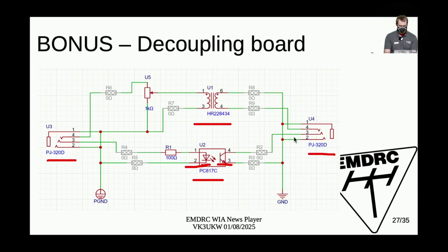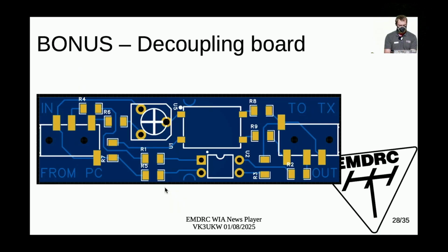You've got a whole bunch of 0 ohm resistors here that I put in, so that if I accidentally flip one of the electrical connections around, I can botch it to make it go in the right direction if I need to cross it over. It also let me do the whole board as a single-sided board by routing traces under the resistors, which means I didn't have to worry about the backside of the PCB.